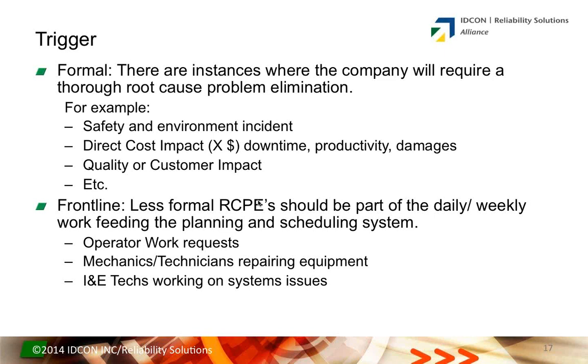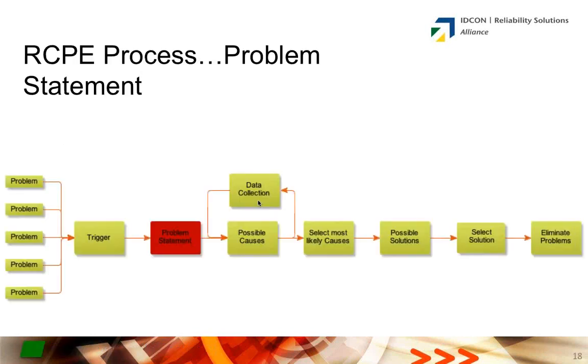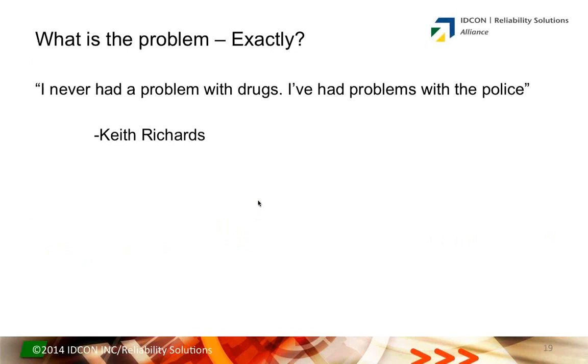A couple of years ago, I did a paper at Ultrasound World on using condition monitoring, particularly ultrasound, in troubleshooting hydraulics. I can tell whether the valve is leaking, or I can tell other issues. So it's very important that we don't just change those parts. The problem statement is really pretty important, and sometimes we're not good at that.